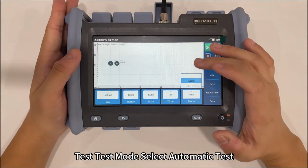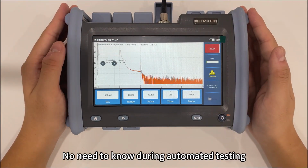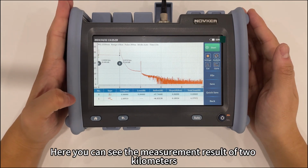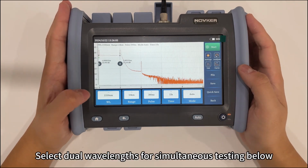First we plug in the backlight fiber. For test mode, select automatic test. Wait for the test to end. During automatic testing, there is no need to choose the test range and width. That is, just select the test wavelengths. Here you can see the measurement result in kilometers of optical fiber. Select 2 wavelengths for simultaneous testing below.